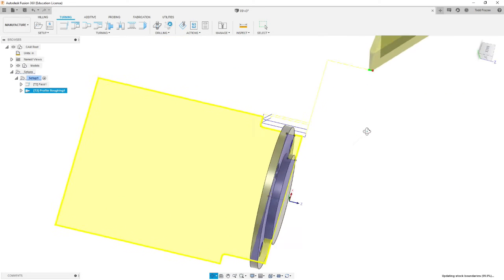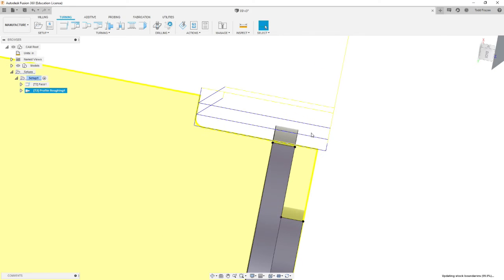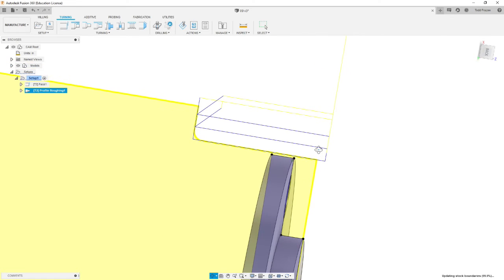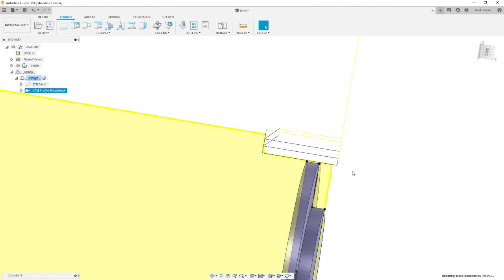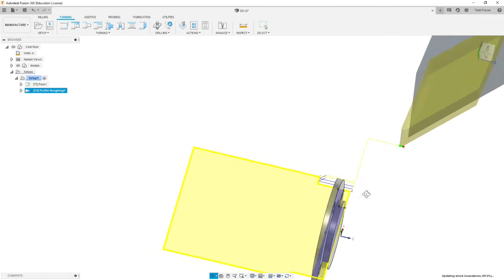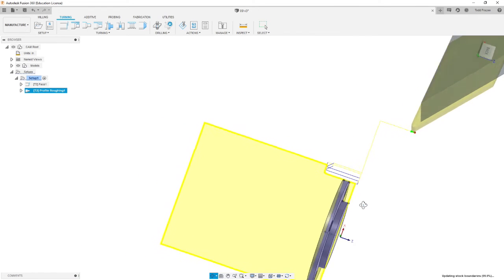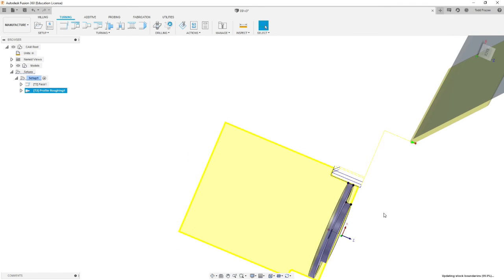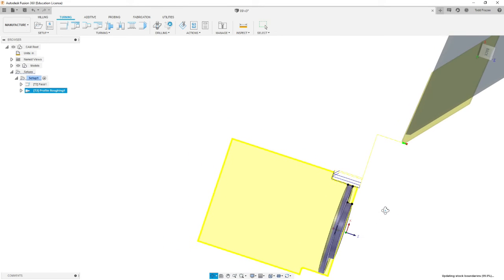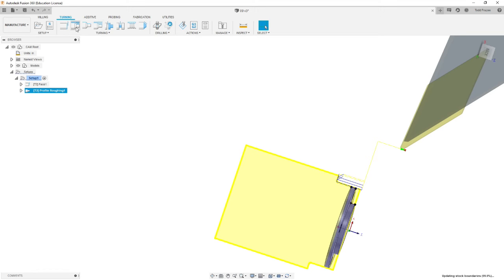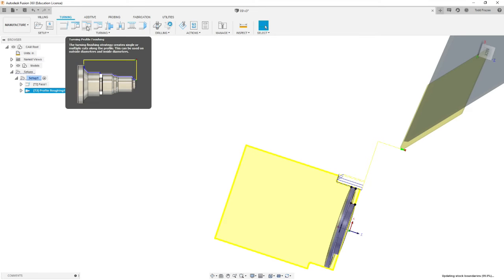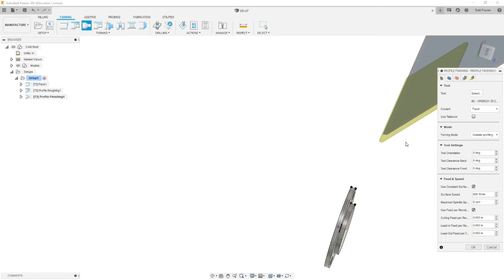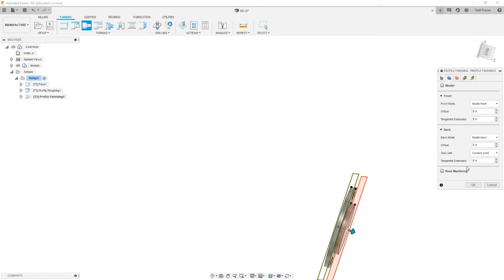Alright, so we came in and we took a couple passes and then did a final roughing cut, leaving 4/1000 for a finishing routine. Okay, so we've machined the face. Now we've machined the outside diameter, major diameter. Now you go onto the turning finish profile, and we want to base this off the same tool, same feeds and speeds.